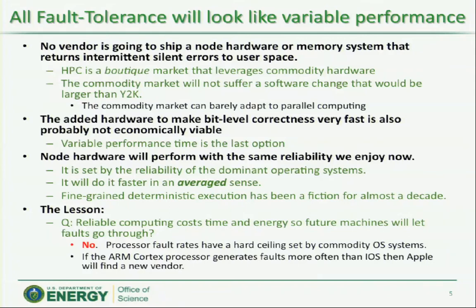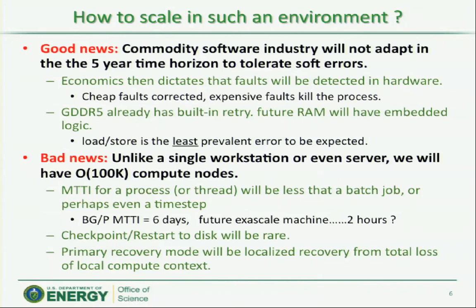Well, how much does it cost to correct an error, and how much does it cost to detect an error? Detecting an error costs a lot less in terms of silicon. It allocates anywhere between 20 to 40% of your silicon on die to have a fairly robust soft error detection mechanism. So you can detect the soft error, and you do what the other generation of machines will be doing, which is